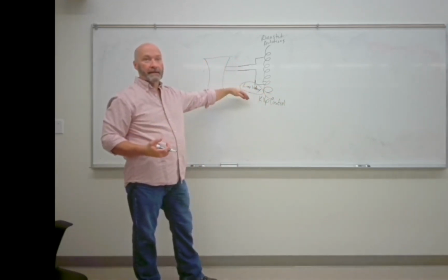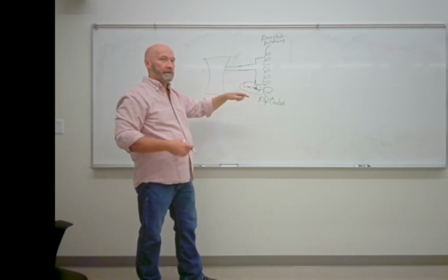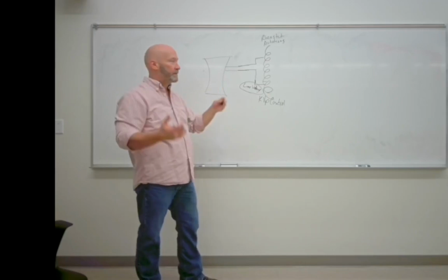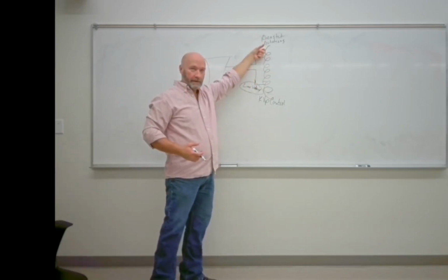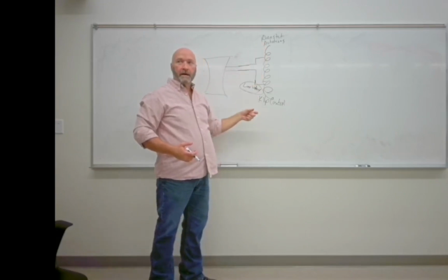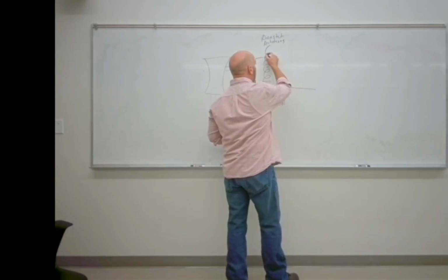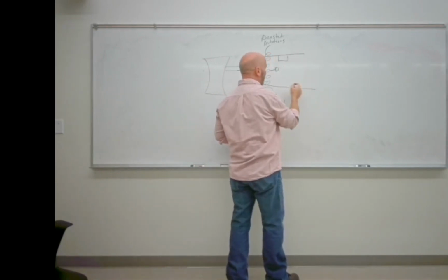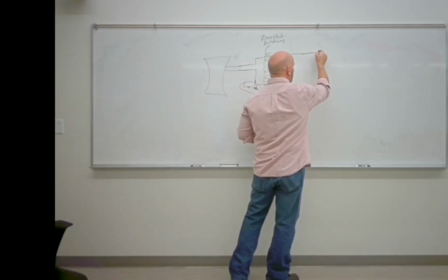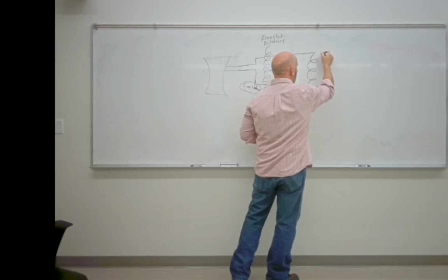It's still registry testable, so you need to understand that there is a line voltage compensation circuit that takes out the fluctuations in the voltage before it gets to the autotransformer, which is where we set our kVp, right? So it's going to come out of that, and we've got some other things in here that we're going to plug in later on. And it goes out of that and it goes into the thing that creates our high voltage.